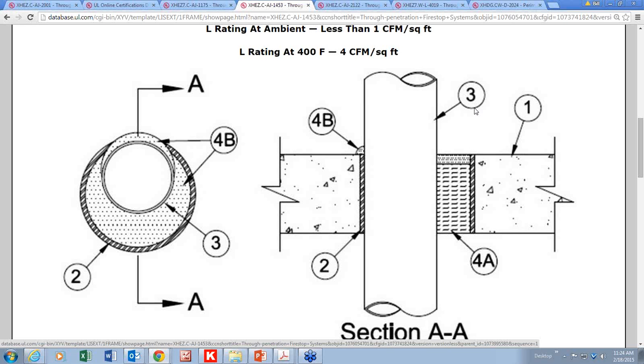Same thing with copper for plumbing. You're trying to isolate the cement-based material, which will eat a copper pipe or cause galvanic corrosion. You isolate it using a sleeve. But most mechanical and plumbing engineers extend the sleeve 2 to 3 inches above the floor so that if water piles on the floor, they don't get a leak down to the floor below.